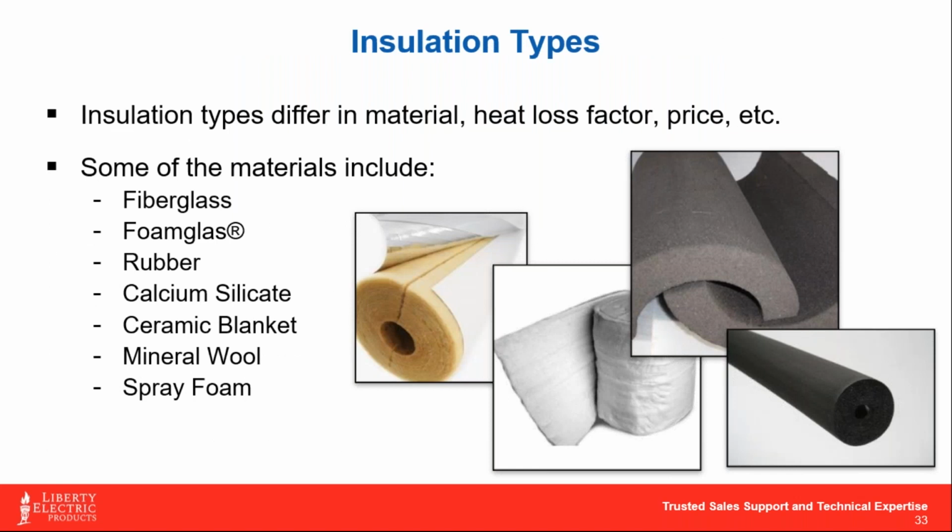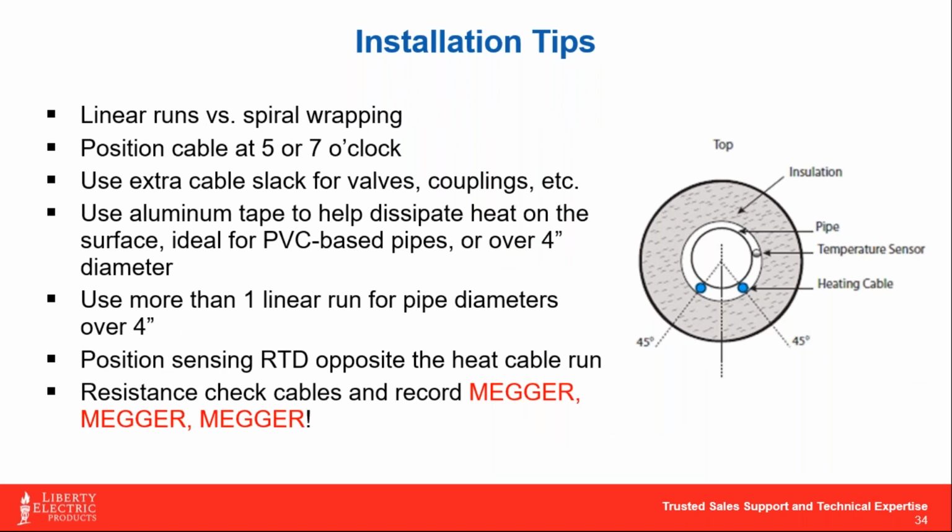Just a couple more slides here. I know we're basically at our point here, but here are a couple of common insulation types. In most cases, I don't think you need anything exotic, but as long as you've got at least an inch of insulation, and that's what we shoot for, an inch to an inch and a half, it will usually take care of you just fine in most of these applications. Once you start getting over an inch and a half, it starts getting pretty expensive anyway.